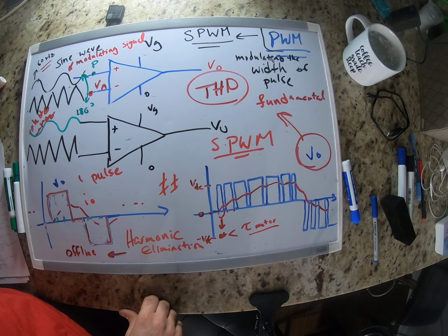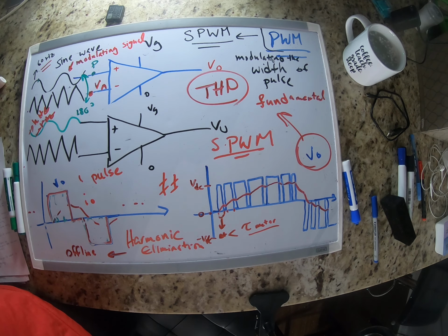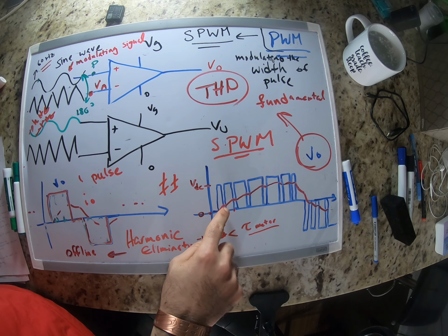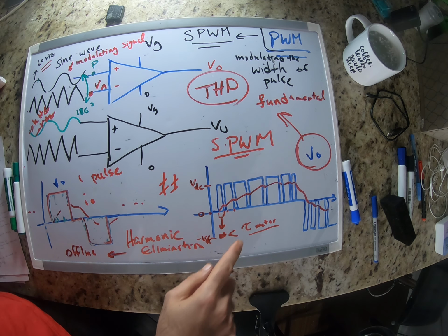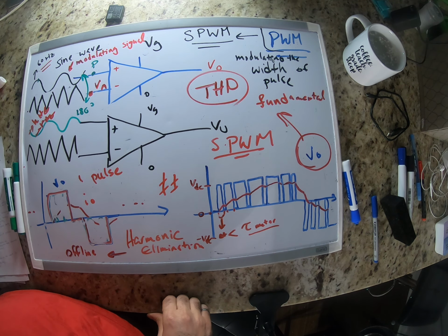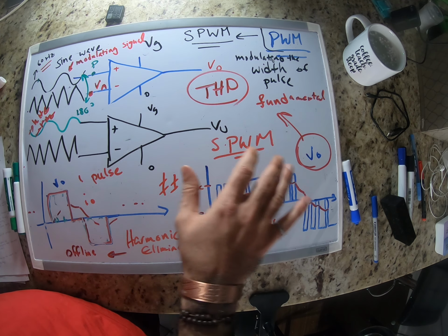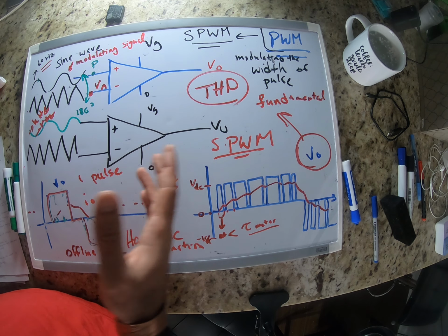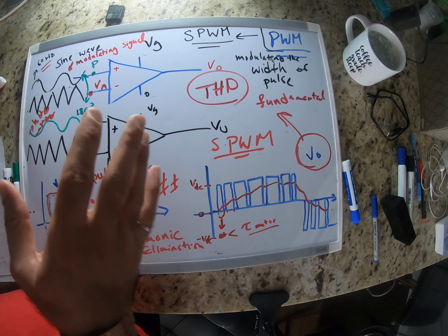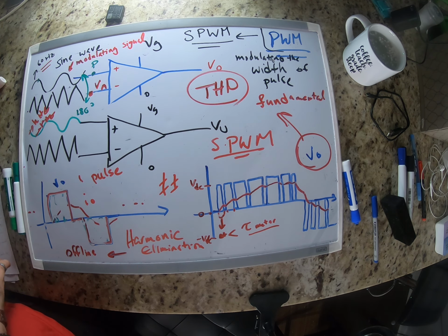We wouldn't have overheating. One thing that we would have using PWM is a lot of switching losses. You remember that we calculated switching losses for DC-DC converters. So here we also have switching losses, and that's something we have to consider. Also, using an inverter, we would have harmonics. We still need an LC filter to filter out the harmonics, based on the standard, which harmonic to what level we have to filter.